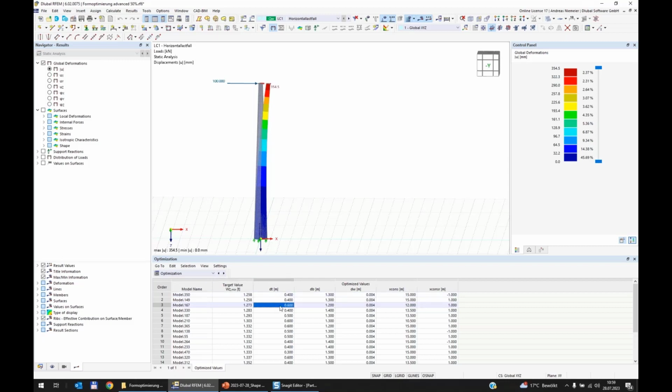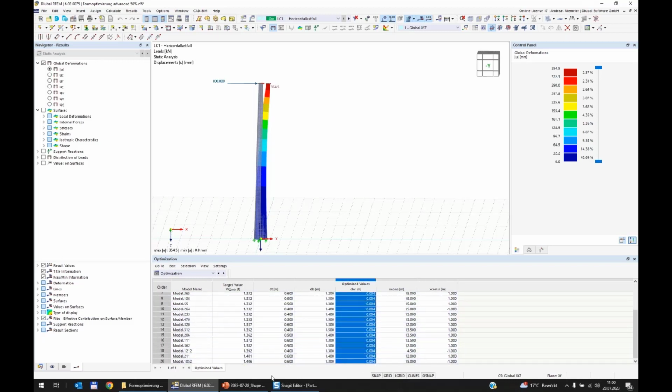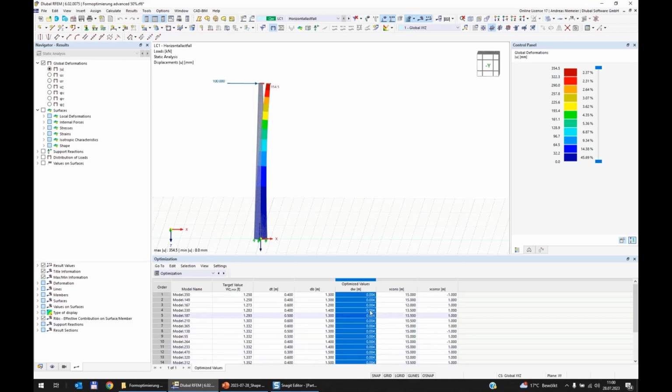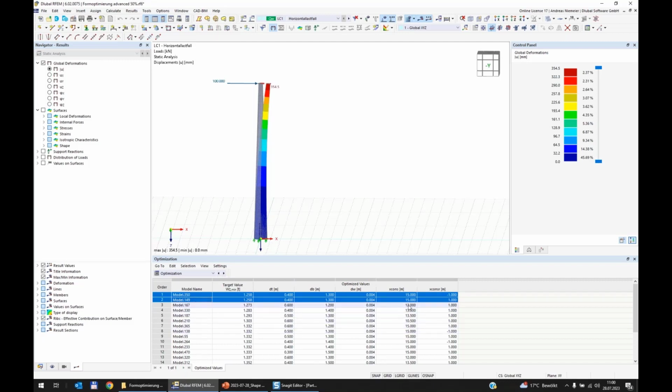where the top diameter is 60 centimeters and on bottom 1.2 meters, 4 millimeters with a constriction at 12 meters in direction 1. So constriction has some effects. Also the direction, you see it's changing minus plus minus plus. It also changes the X place. But what is really governing is the thickness. It is really sensitive. I think all 20 solutions that I stored have only 4 millimeters. So this is a really designing parameter, and the others also have some effects. But this is the result, finally, that you get from the program.